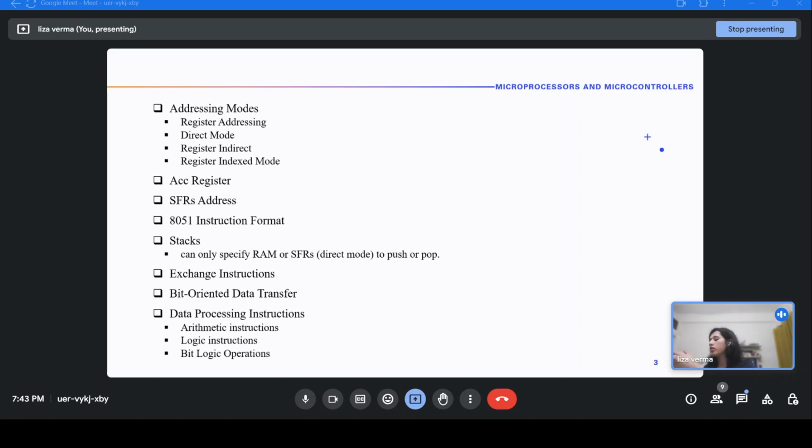So we can have instructions like SETB, where you specify the bit or the address of the bit that you want to change, CLR, and CPL for complement. I guess there are 12 instructions in 8051 to affect individual bits. I don't have the list here, but you can search what those 12 instructions are. But mostly you use set bit, clear bit, complement.